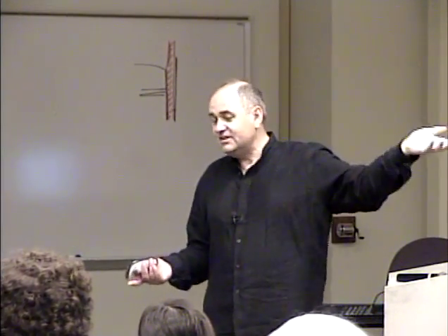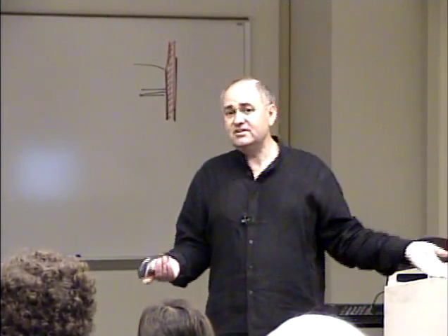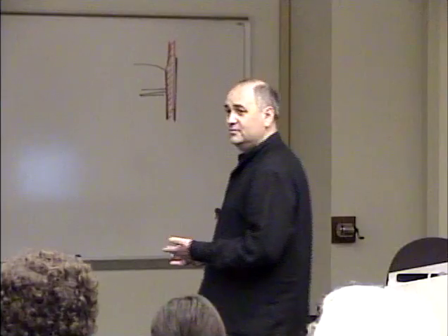This is why when we fly passenger planes, we don't fly at 50,000 feet, but at 30,000 feet, about 10 kilometers above the ground. It would make sense to fly higher if we were able to create lift there. Why? It would be cheaper. Why? Because there is less drag. Correct. The higher we fly, the less drag there is, so less fuel will have to be consumed. The problem is that we don't have lift there either.